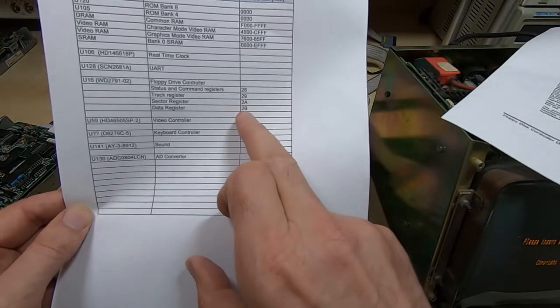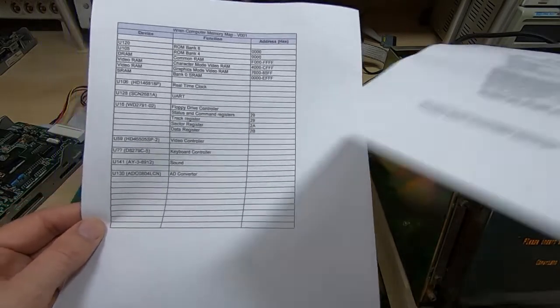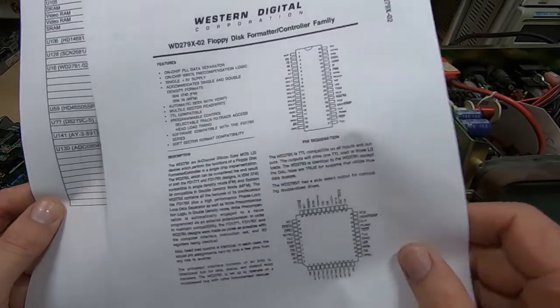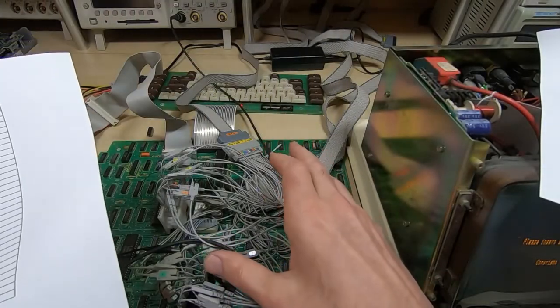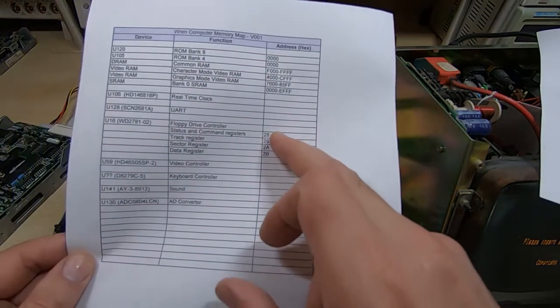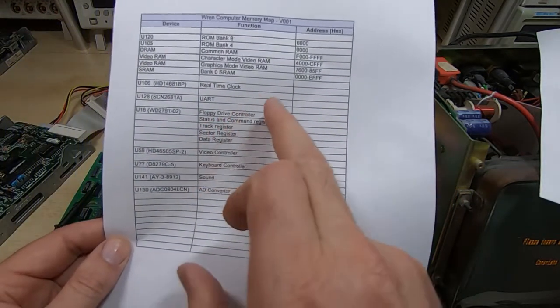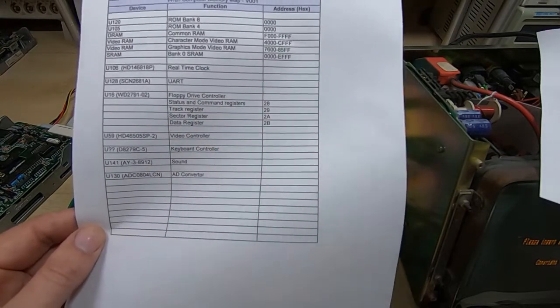However, we never got a hit on register 2B, which, if you look at the spec sheet for the device, is the data register. So although we were getting responses and data coming back from the other three registers, which are the status, track and sector registers, the data register was never